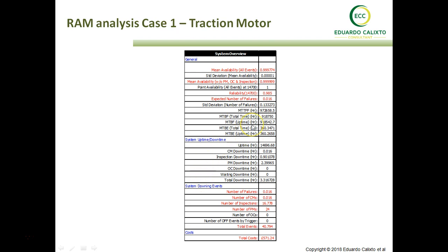In addition, we know that it depends on the PDF. If you have a Gumbel, for example, that is skewed to the left, and you apply the MTTF index as a reference to implement some preventive maintenance, probably we'll do the preventive maintenance either too late or earlier than necessary. And if it's earlier than necessary, you do not detect any failure, and if it's later on, the failure will happen before you prevent the failure.